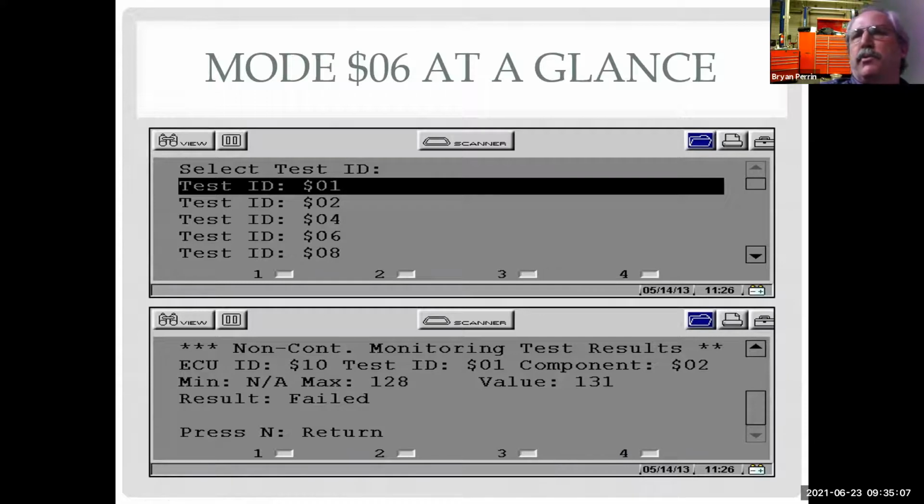That's a plausible result. Time to go test the Cali converter, time to go test for exhaust leaks, O2 sensors, all that stuff. What I do know is that the Cali converter is not hollow. I know it's not completely dead. And I need to make sure that it's not something like an exhaust leak or an O2 sensor or fuel trim problem affecting the converter's efficiency, that maybe if I fix those, the converter is going to test good and not need to be replaced.